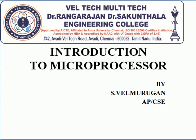And then the second one is ASIP. The instruction set is designed for a specific application. The best examples are the DSP, digital signal processor, and the 8051 microcontroller. And then the third one is a combination of both. It can use both application-specific and non-specific instructions. The best example is the 8087 coprocessor. And the remaining processors, which can execute more than one instruction simultaneously, are called dual core processor, multi core processor, etc.